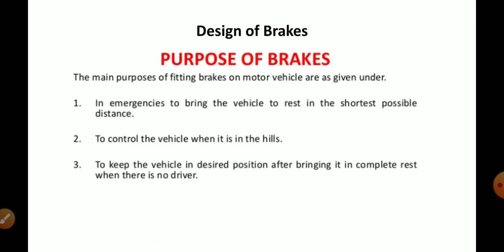Now, the purpose of the brake. The main purposes of the brake are: in emergencies, to bring the vehicle to rest in the shortest possible distance; to control the vehicle when it is on a hill; and to keep the vehicle in the desired position after bringing it to complete rest when there is no driver.